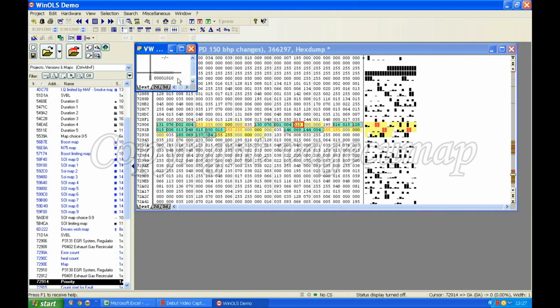And from looking at some of the other files that I've been searching through over the years, and again, it's very difficult to make hard and fast comments, because sometimes you work something out perfectly for one file, you do the same thing in a different file and it doesn't work. But I think that the one there represents 2, because 10 is 2 in decimal, and I think that means that the mill light should be on, and I can't remember what that one is, but I think that that's what's going on there.